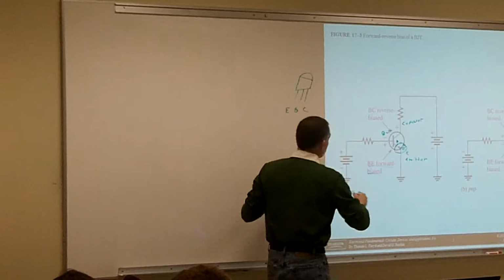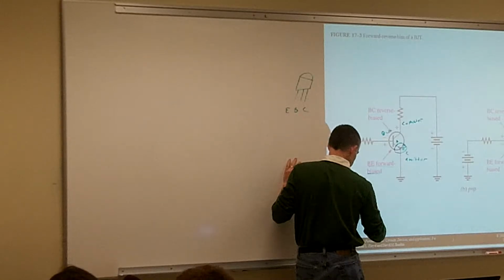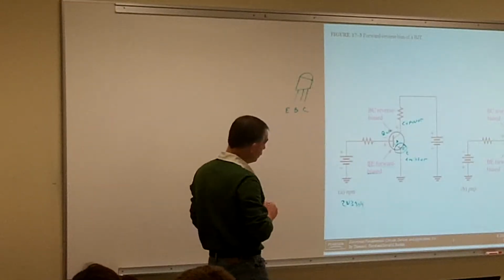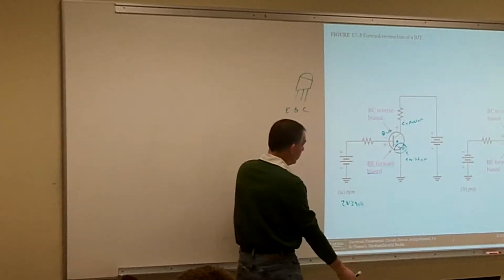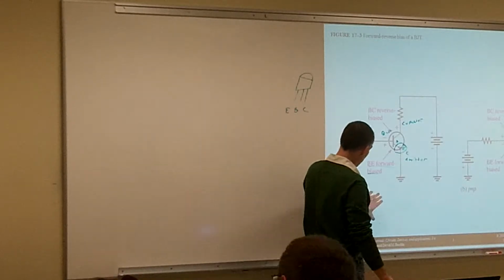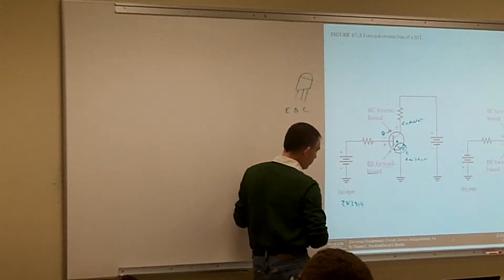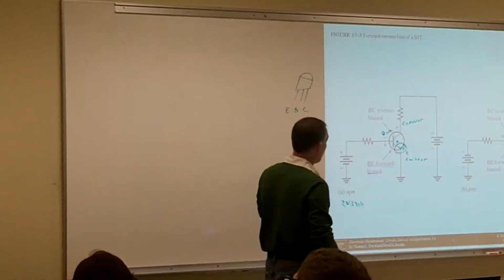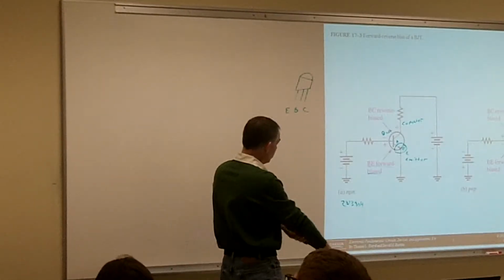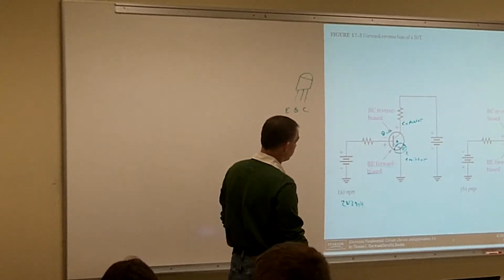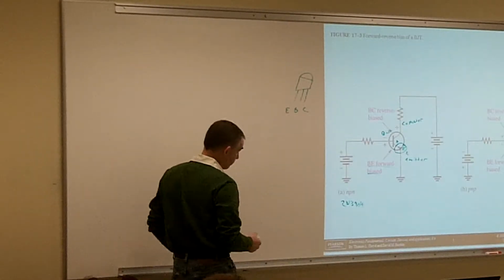Coming out of our transistor, the NPN that we're going to be using is a 2N3904. That's our general transistor that we typically use, but there's a lot of different transistors out there, some of them with better frequency response. For general applications, the 2N3904 is the one we use. If we just want to turn on an LED, or amplify a signal, then we use the 2N3904. If we're using something with high frequency or need a certain amount of gain, we may go with a different type of transistor.